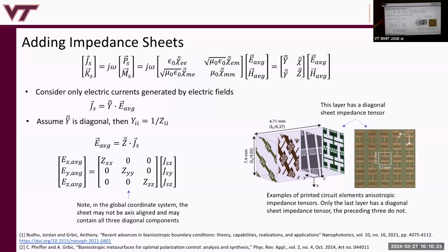So this is the bianisotropic boundary condition here. And what this represents is a particular, you know how we derived boundary conditions in the last class, right? We said we wanted to account for the tangential discontinuity in the fields. In the case of H discontinuities, we define the current density J. And in case of the E discontinuities, we define the current density M. So because of the equality that links those two, the current densities to the discontinuities in the fields, if you have a discontinuity in tangential H, then there must be a surface current present. Conversely, if you have a surface current along a surface or an interface, then the magnetic field must be discontinuous, right? Okay, this is a similar boundary condition in the sense that it's defined at an interface.